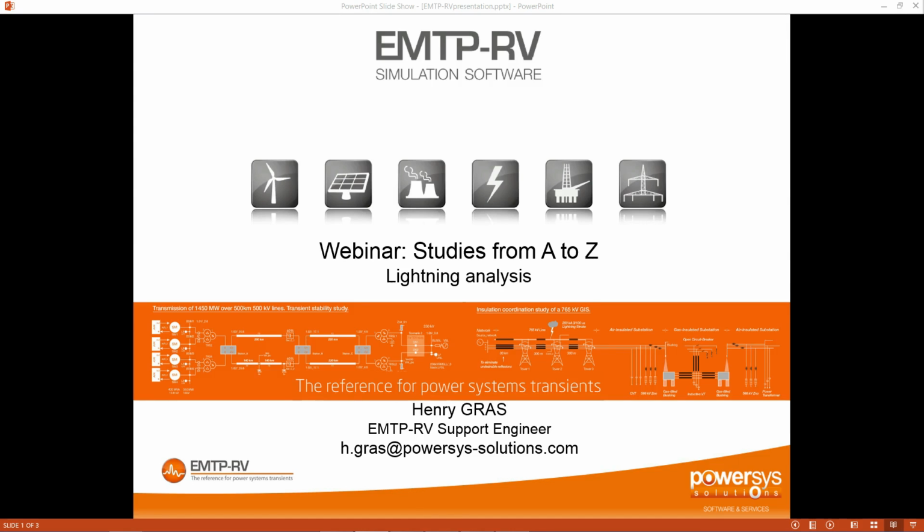Thus, I will show you how to build a frequency-dependent model of metal oxide surge arrestor following the IEEE standards, how to create a suitable model of tower which considers propagation of the surge and air gap leaders, how to build a frequency-dependent model of line, and finally, how to include the equipment of substation, including transformers, CVD, conductivity, for fast front transient studies.